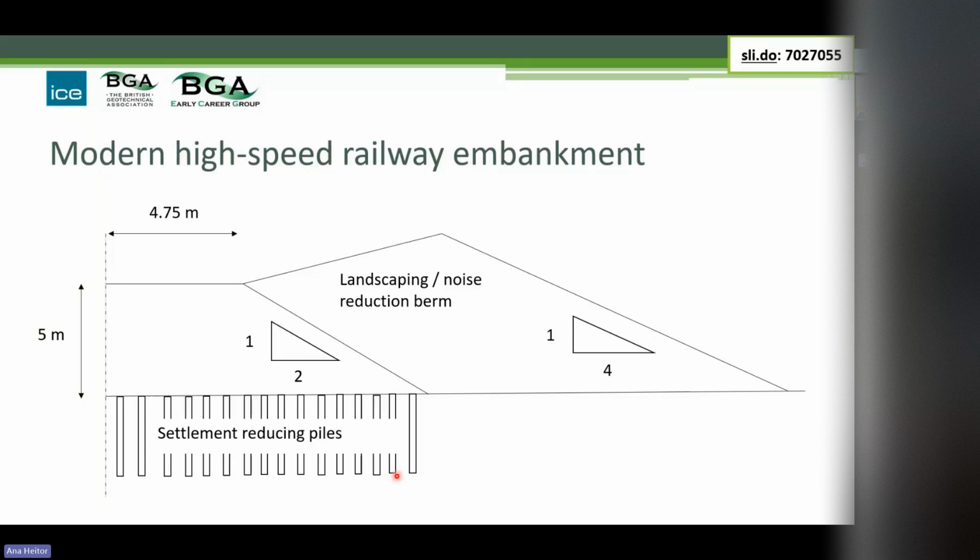Well, we know that consolidation and swelling happen quickly at the start. So if you pretend that nothing's happened for the first year or 2 years while you're building the thing, then of course you're going to over predict the actual amount of settlement or heave. So my line was, I could do a slightly different calculation that said 28 millimetres, then we wouldn't need any concrete at all, would we? And there was a sort of begrudging acceptance of that.